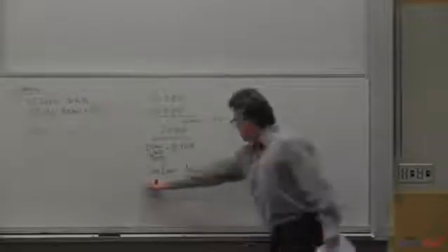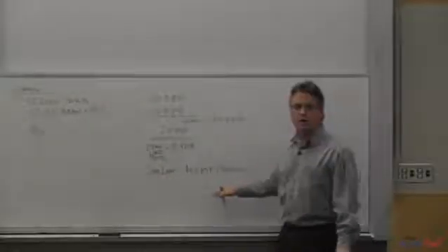So we're doing a parking structure. The code tells us that's 40 pounds a square foot, and that's unreducible.